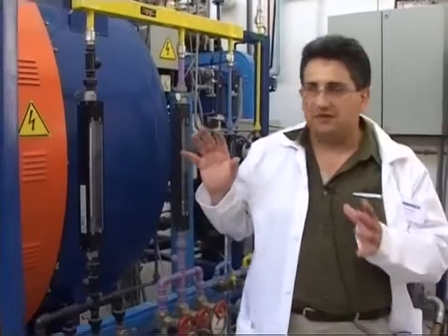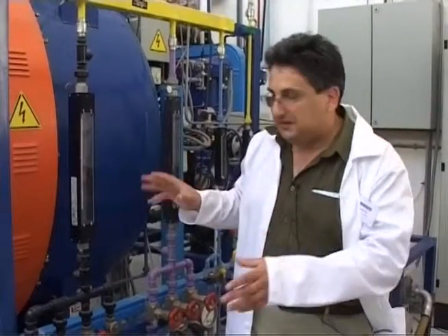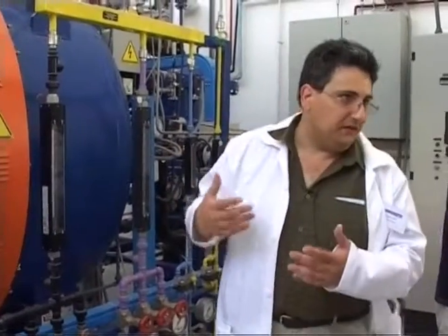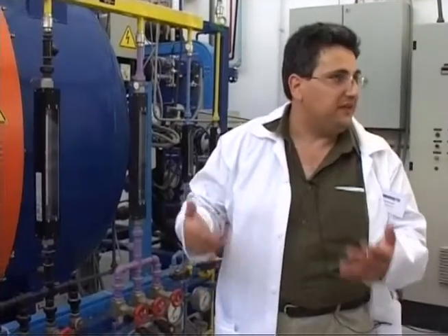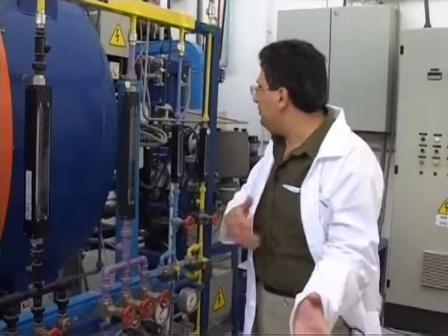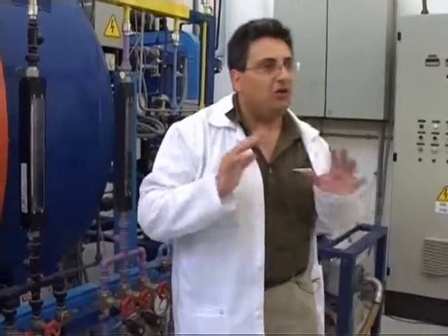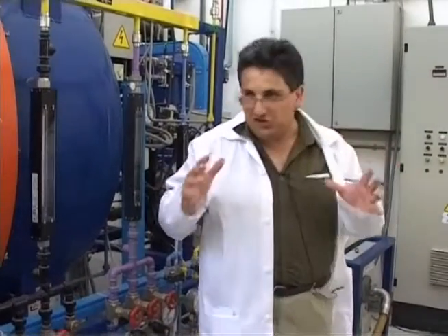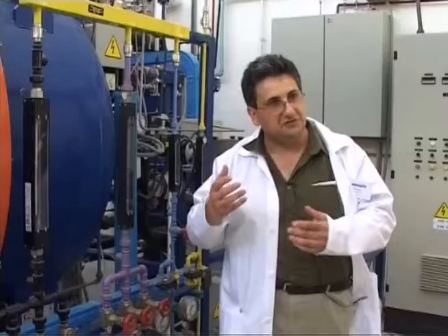Otherwise, an explosive mixture is generated inside the furnace. So the first step is to evacuate the air from the furnace and rinse the vacuum generated with nitrogen. The nitrogen is afterwards pumped out so that all the original atmosphere inside the furnace is removed.